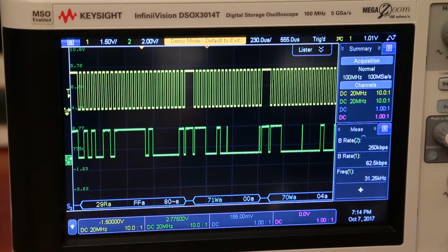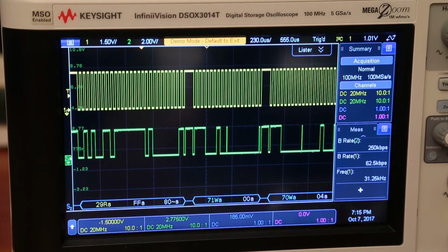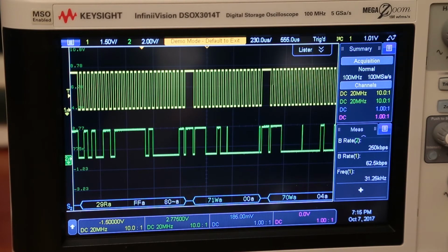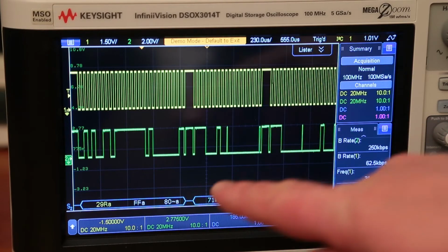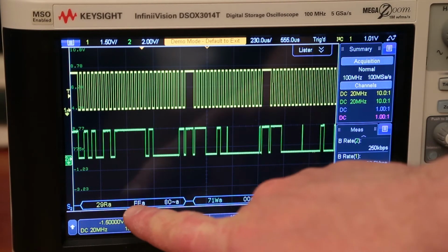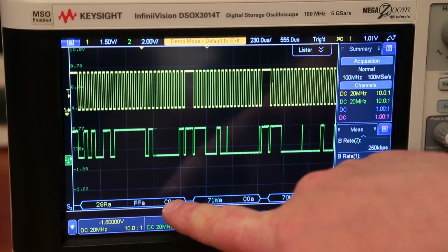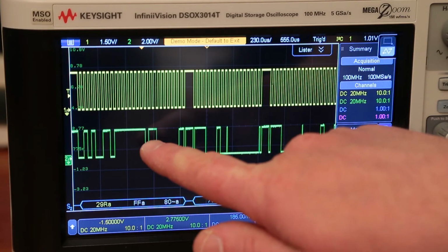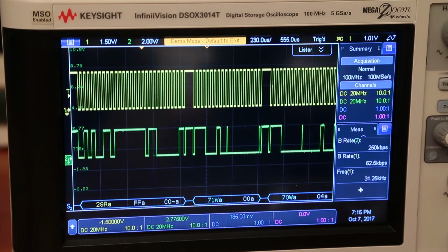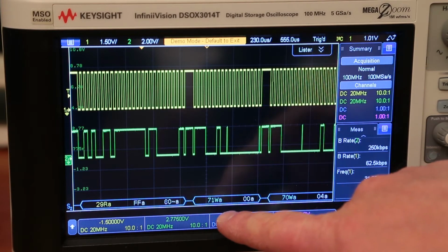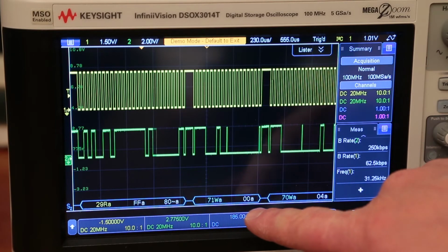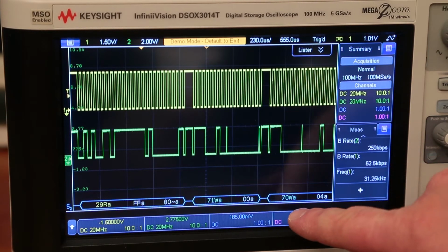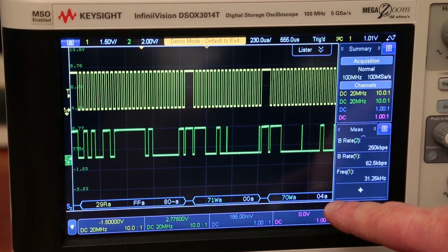So I've got this to trigger on a 29 read with acknowledge, with the first data bit being FF in hexadecimal with an acknowledge. If you then look, you'll see that the second bit of data in that same stream, which is over here, so 29 read, acknowledge, data's FF, acknowledge, that's an 80 and a C0 with an acknowledge, and the bit's changing. In their demonstration you can see the bit actually moving and changing pretty quickly. You've then got the next bit in the stream of data coming through, which is 71 write, acknowledge, 00 acknowledge, then 70 write, acknowledged, 04A acknowledged.